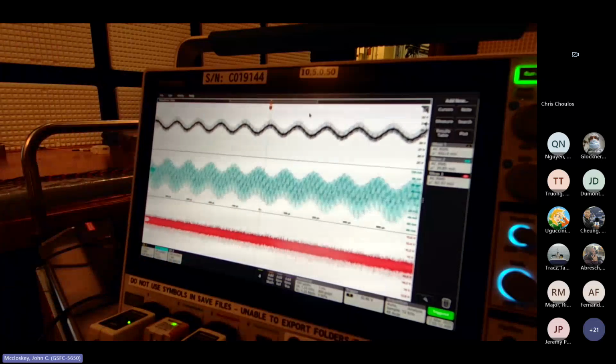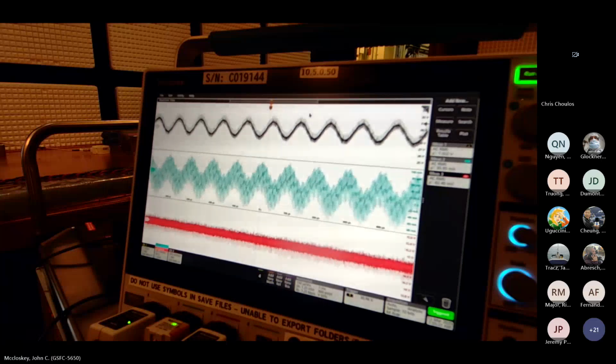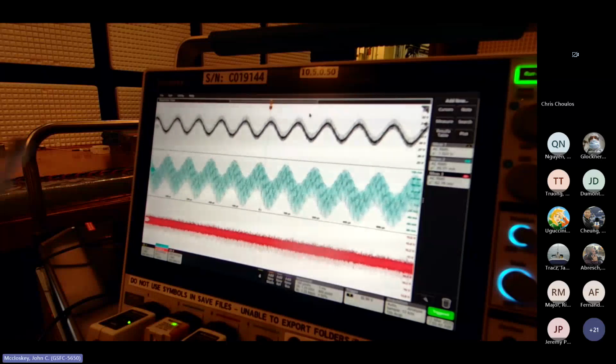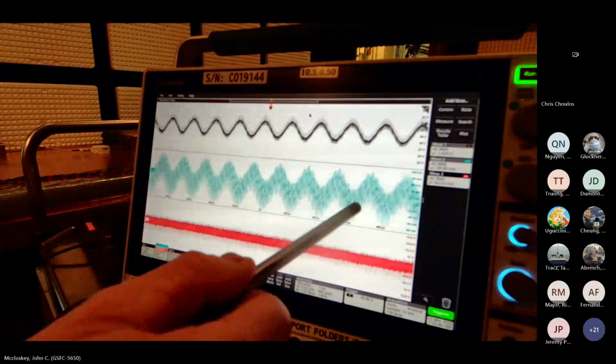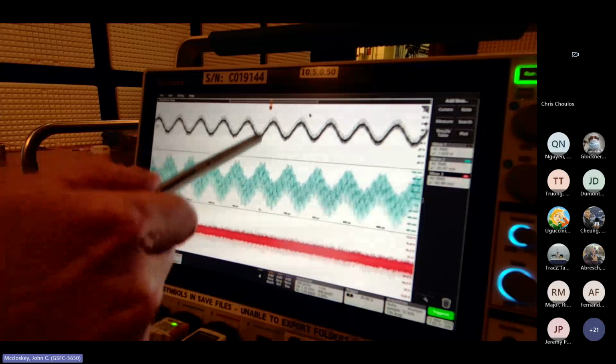But anyway, so we'll crank the signal up to get our 1 volt. Okay. I'm going to call that close enough. That's 1.02 volts. So minus 31.2. It's actually about the same as it was at 1 kilohertz. So about 1.02 volts, and the current is about 35 milliamps. But you can definitely see the contour of the current coming into play here. And you can also see a phase relationship between the current and the voltage.